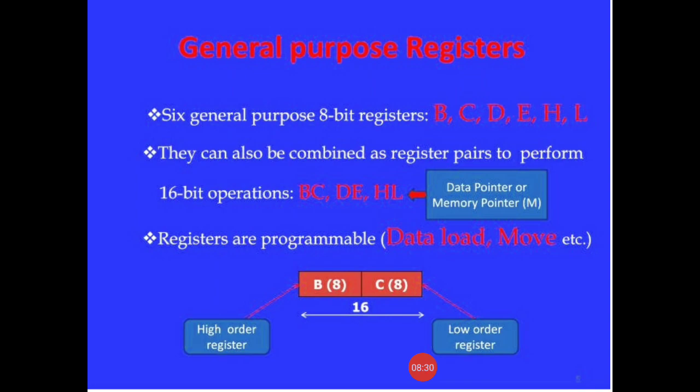To store and read data from these registers, bus access is not required, as it is an internal operation, as these registers are residing inside the microprocessor. So we do not need any bus operation for accessing these registers.